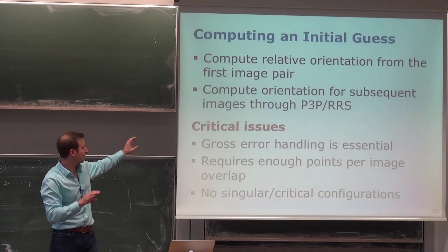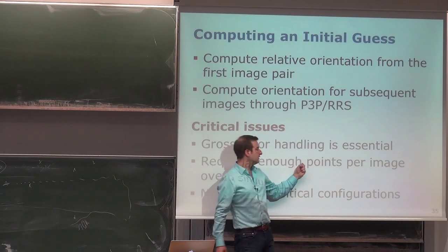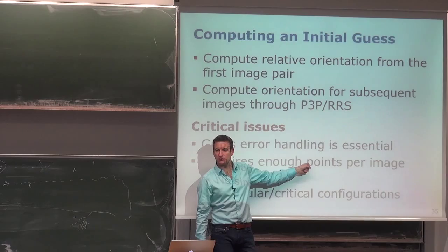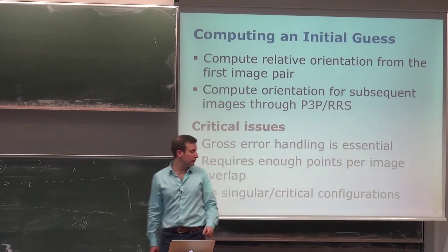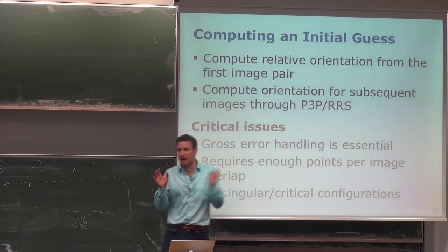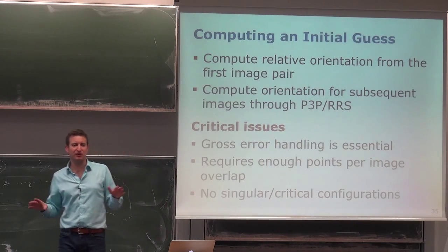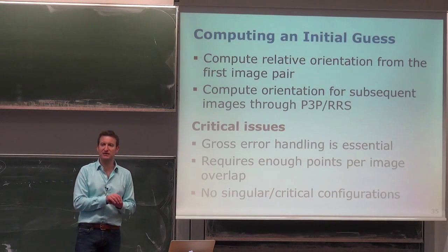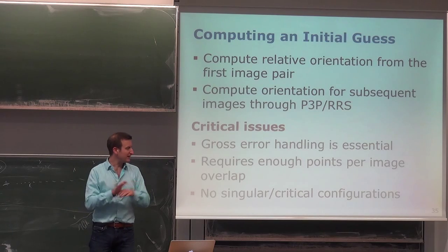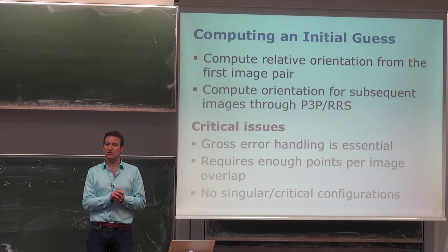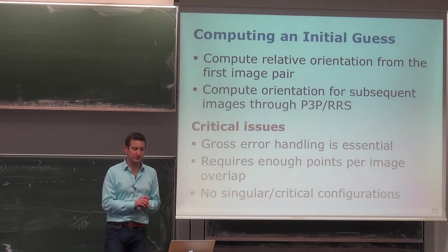That's how this was meant. So it requires enough new points or non-control points, otherwise that would eliminate all the advantages from the bundle adjustment if I would have enough control points. Not all advantages, but eliminate one of the key advantages that we discussed before, that we only need a small number of control points for bundle adjustment.